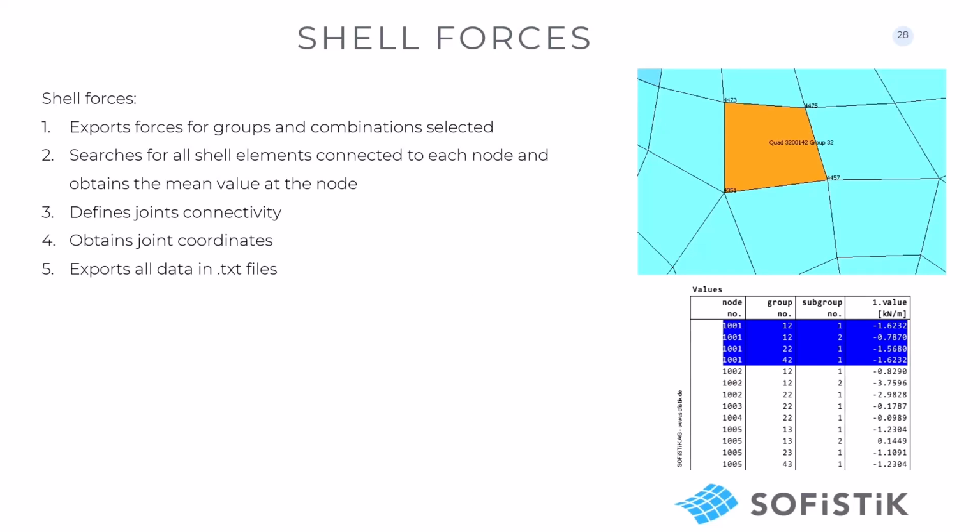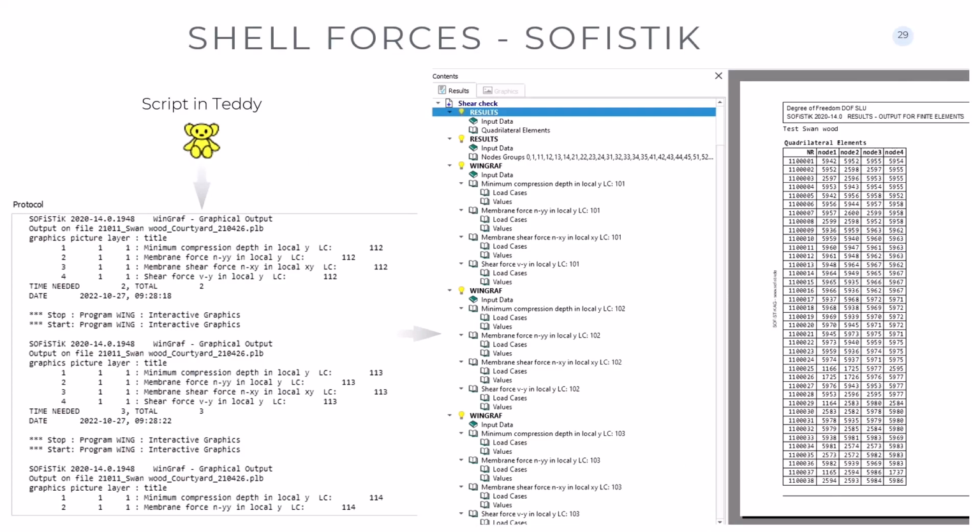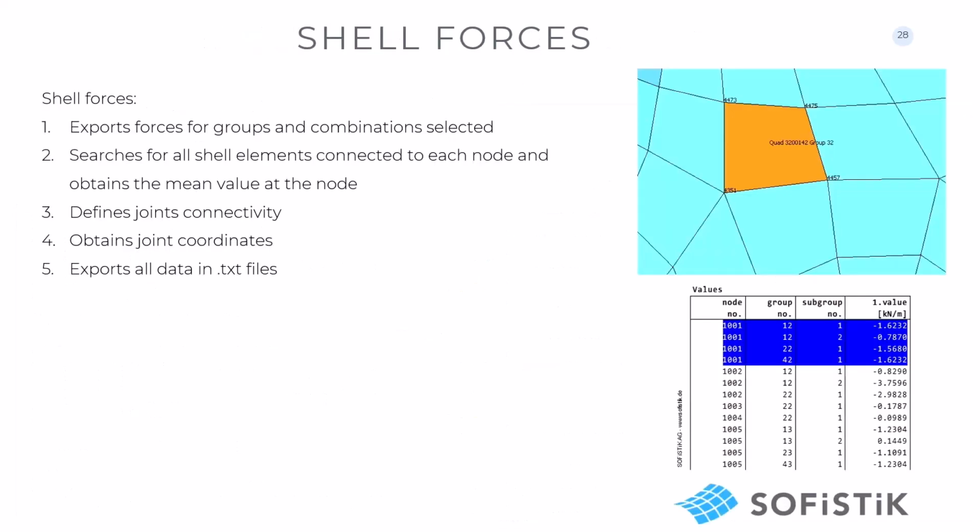And the length, in theory, every fabricator says to you that is almost whatever you want, because these things go in a machine that presses it after gluing it. So essentially, you can extrude, in theory, as much as you want, but in reality, for physical reasons, you have to transport it. I think the longest they have produced is 30 meters, but more than that is very tough. So whatever building you have to split it in modules of, let's say, roughly 2-3 meters, thickness of 200 millimeter, and then length, yeah, ideally 10-15 meters, not more than that, if you want to transport it.